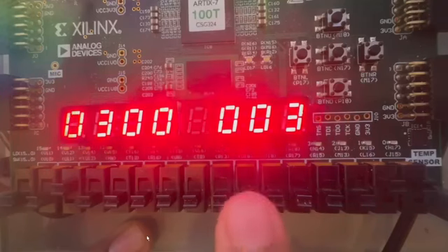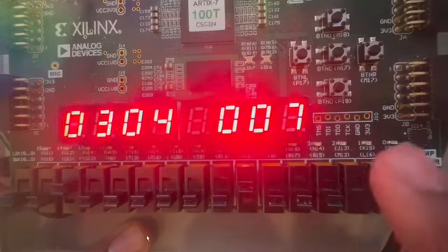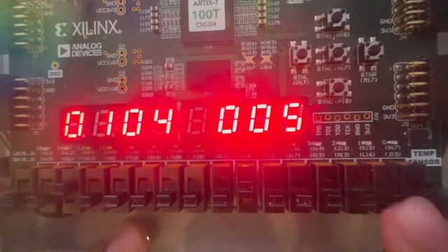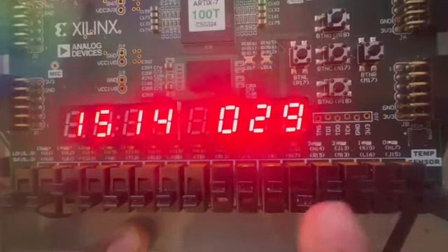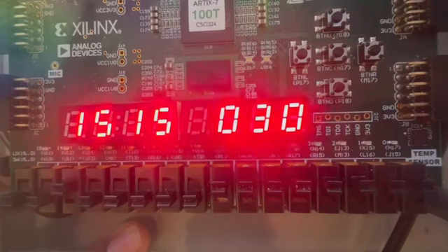As you can see, addition is currently selected with 001, adding up inputs A and B, converting them from binary to decimal and then displaying that decimal value on a 7-segment display. Since the inputs are 4-bit values, the max value for each input digit is 1111 in binary or 15 in decimal.